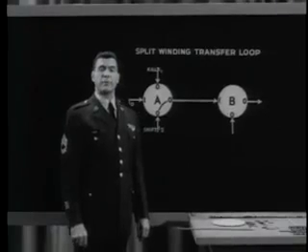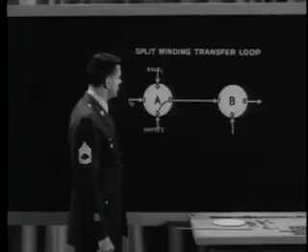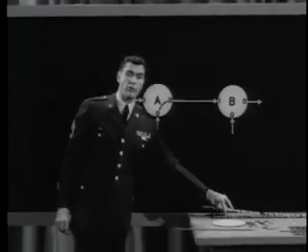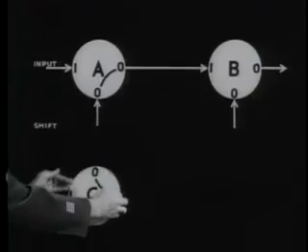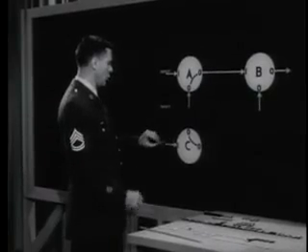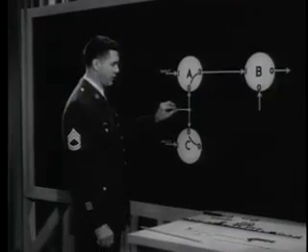The third transfer loop, the inhibit transfer loop, is really a variation of the split winding transfer loop. It offers the same kind of isolation between the sending and receiving cores, plus an additional means of control over the transfer. We'll need only two inputs to core A: the input pulse that switches core A to binary 1 and the shift pulse. But we'll be using 3 cores. The third core, C, has its own non-dot input, and it shares the shift pulse with core A.